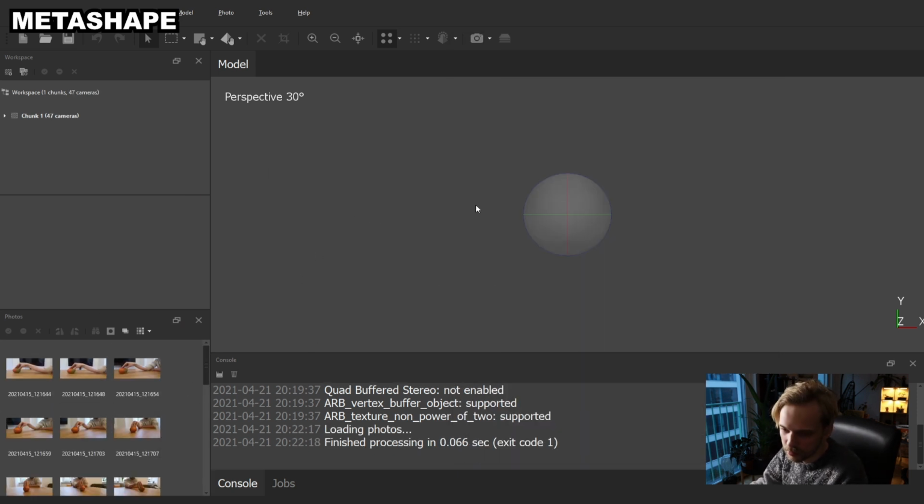And now I need to start first of all finding pairs of images that work together, or match pairs, and then create a preliminary point cloud from them, and then create a dense cloud, and then mesh the dense cloud, right? These 4 steps, and also texturing, so these 5 steps, are basically the main ingredients to any kind of photogrammetry software. So knowing that and being a total noob, let's try and figure out where these things are and what to click on.